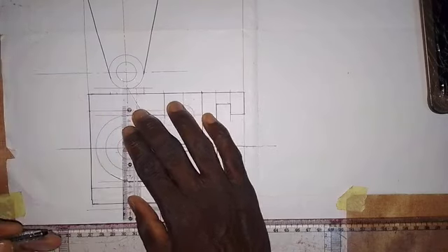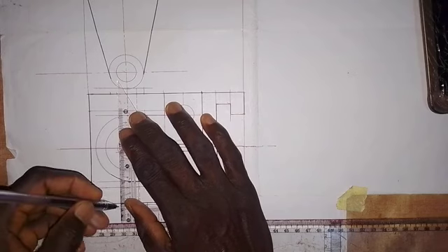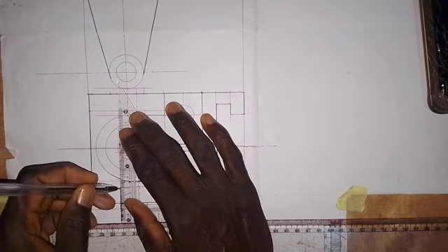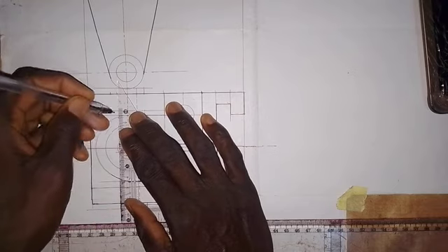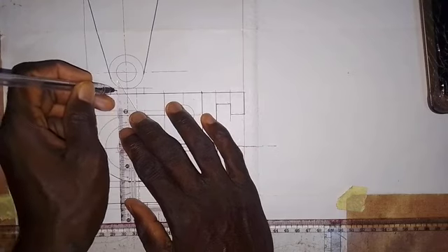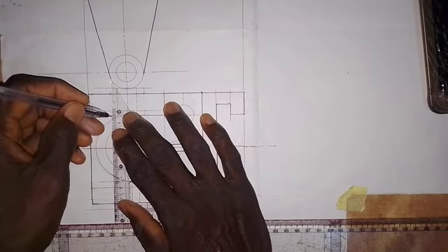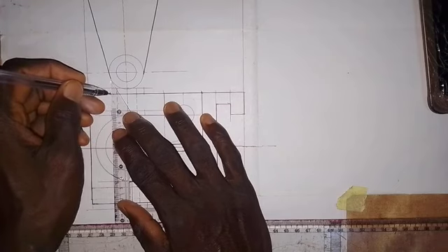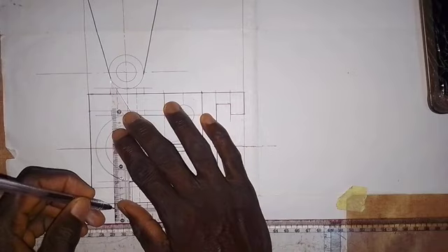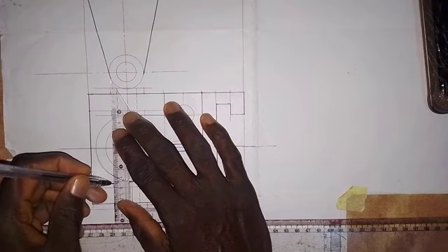Coming here also, we do the same thing. It will be hidden, so we draw short dashes line for the inner one. It is a hole that will be hidden from us. So we have this. We do the same thing on this side. It will be hidden from us, so we draw a short dashes line. While for this one, this will be hidden under this. This part covers it, while here we see it as a thick line. We also do the same thing here. You see it as a thick line here, while for here it is drawn with short dashes line.